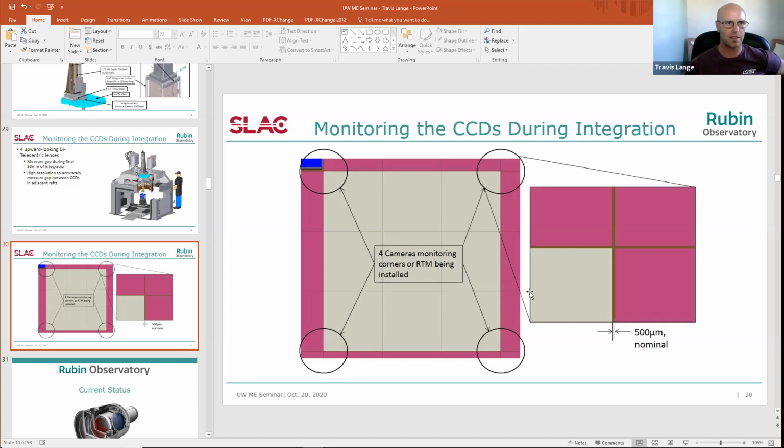And I guess I didn't even mention, the reason for us to have the telecentric lenses, which was very important, is that the depth of field of when it would be an issue for this sensor being installed relative to the one that was already installed was something like 40 millimeters. It's really hard to find something that doesn't give you parallax over that range of depth of field.